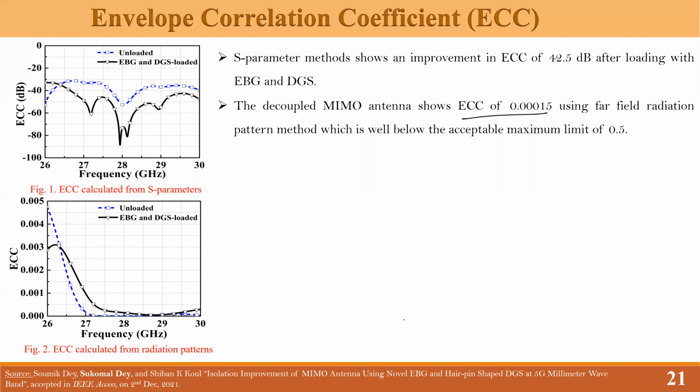I told you there are two types of gain: one is called rate gain, and one is called diversity gain. Whenever you have multipath connections in MIMO communications, and you compare SISO communications versus MIMO communications, the diversity gain plays a very important role. Why?